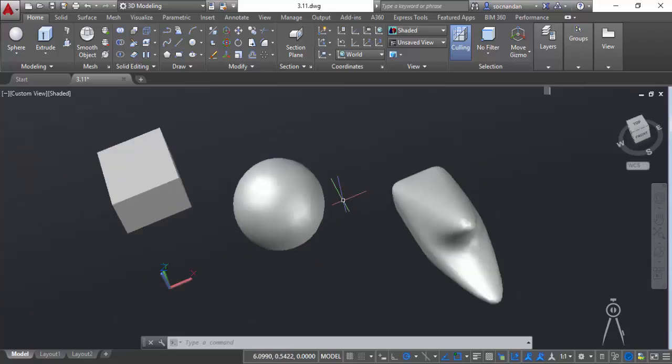In this way, you can create some of the complex geometries which cannot be made easily with the help of 3D solid tools, and you can create those objects with the surface and then later on convert it back to the solid using the thicken command. So this was all about converting an object from solid to surface and making complex shapes with the help of the thicken tool. In the next section, we'll learn about visualizing our solids with the help of coordinates and other tools.